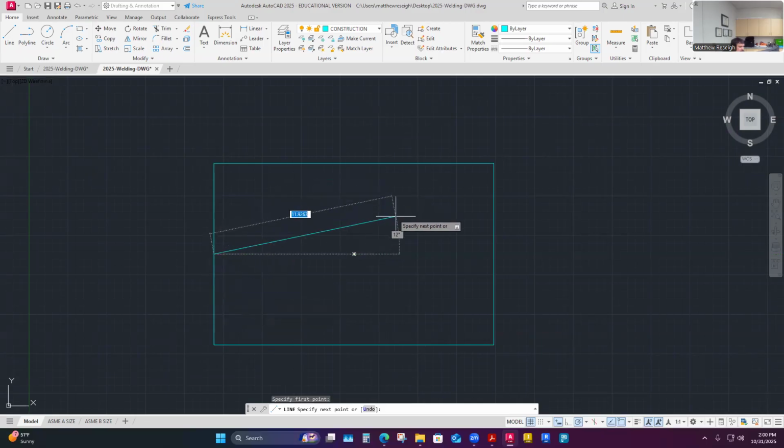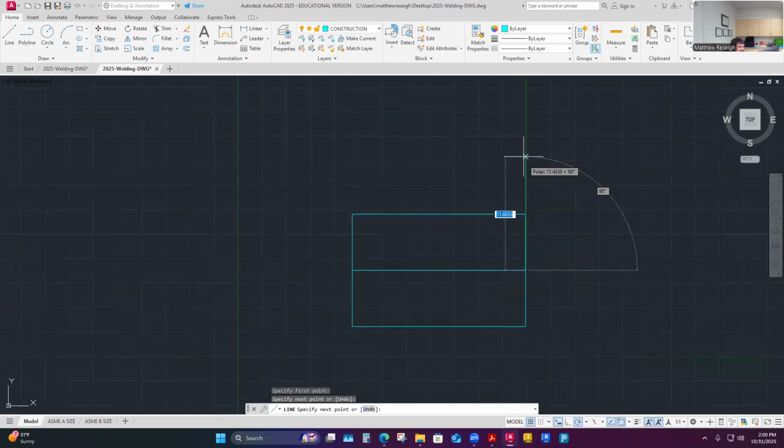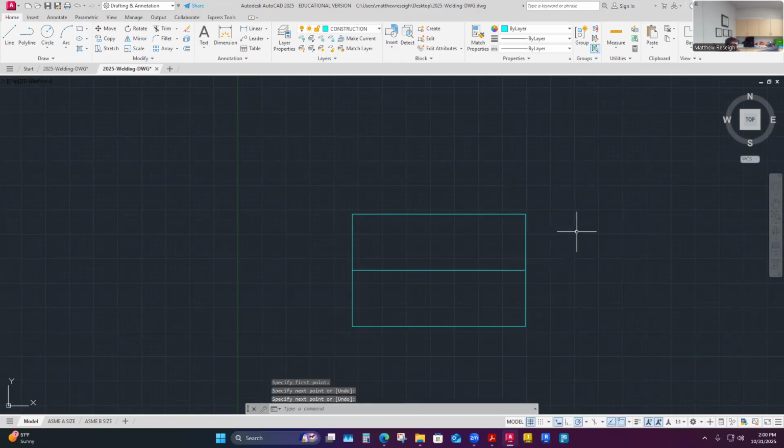And then I'm just pulling across. I'm doing a full center line across here. So I'm going to left click once I get to where it intersects. Pretty much looks like it's another midpoint grip. Even if I got to here, it's going to hit there. Then I just left click again, and it acts like it wants me to keep drawing. Now I'm going to hit enter or right click to get out of the command.